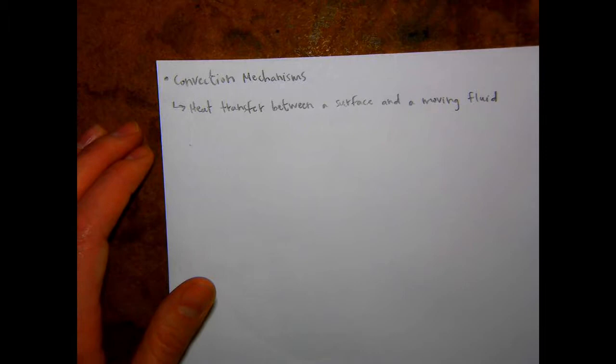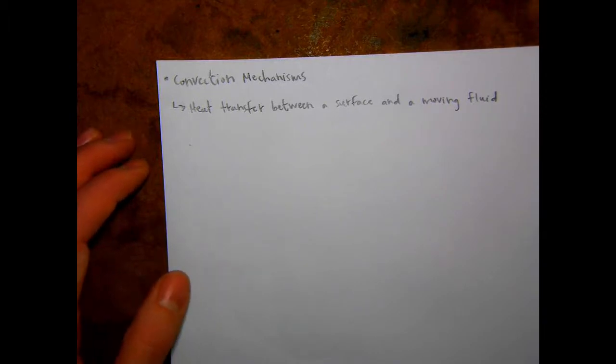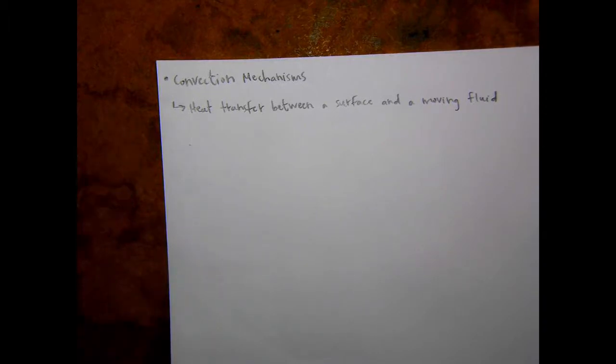And do you remember we talked about the two different modes of heat transfer, or the two different mechanisms that combine to contribute to heat transfer by convection? So really close to the surface, you have primarily diffusion, so the random motion of the molecules is causing heat transfer. And then the bulk motion of the fluid further from the surface is adding to that, taking the heat that's transferred into the flow by diffusion and moving it.